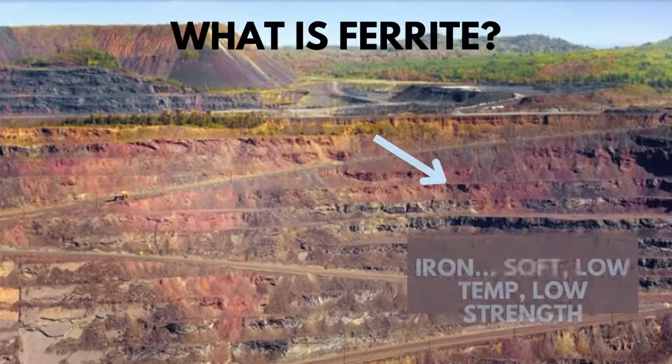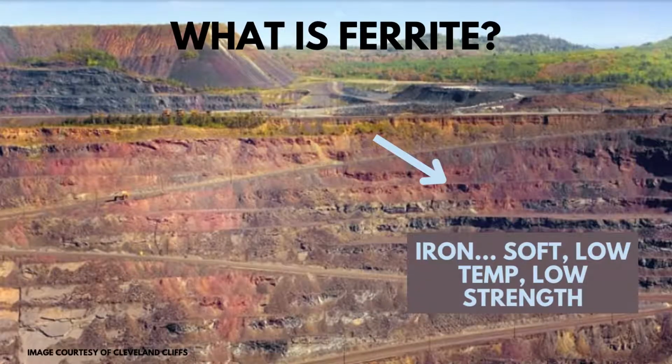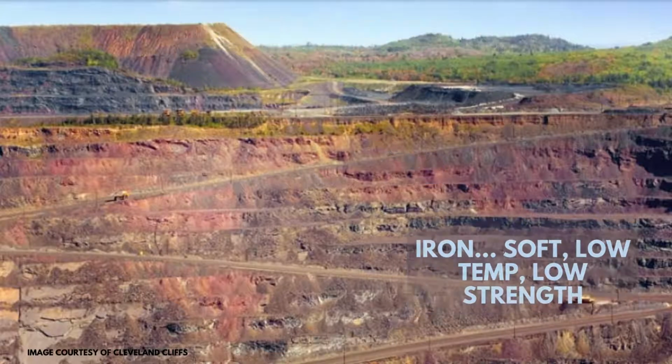What is ferrite? Ferrite simply is iron. Ferrite, as solidified in ductile iron castings, is a soft, low-strength phase that appears in halos around graphite nodules in 2 dimensions, or in 3 dimensions, encapsulates the graphite nodules.